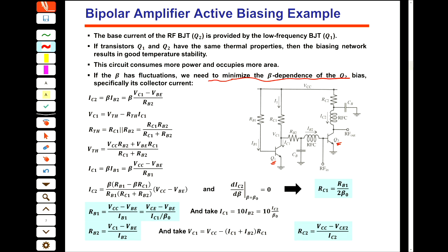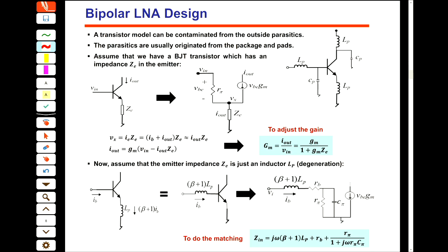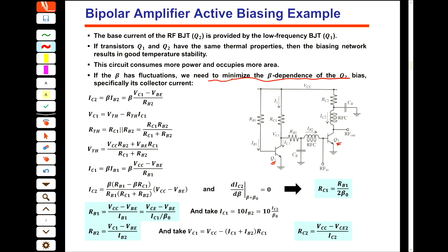And when you put one of them in the circuit, you get one number, and then when you put another, for example, the first one shows a beta of 190, the second one shows a beta of 220. So we would like to bias this circuit so that it has the lowest dependency on the beta fluctuations, because beta is not something which we can control. It's difficult in the process.